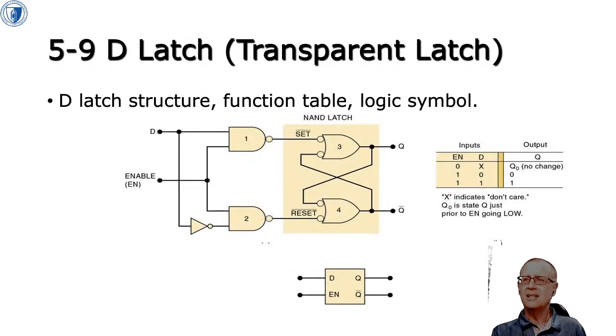And this is the way a D-latch is shown. So rather than having a clock input, it's got an enable input. Right. So if the enable, in this case it's a non-inverting input, if the enable is 0, then nothing changes on the output.